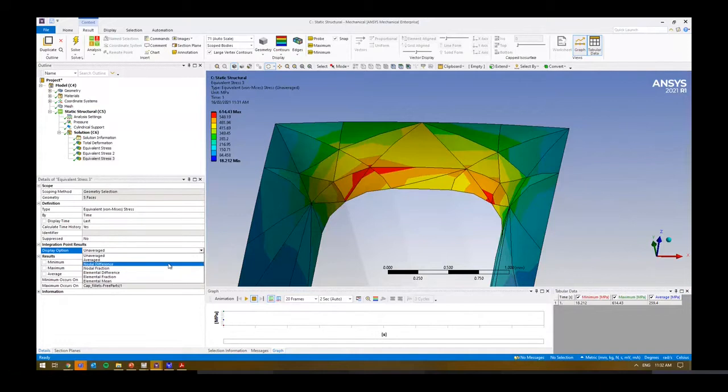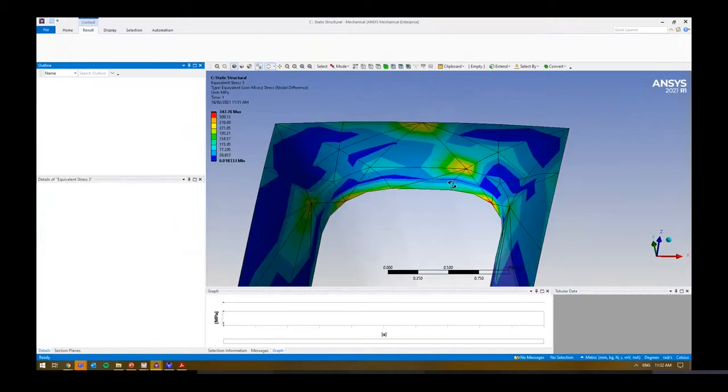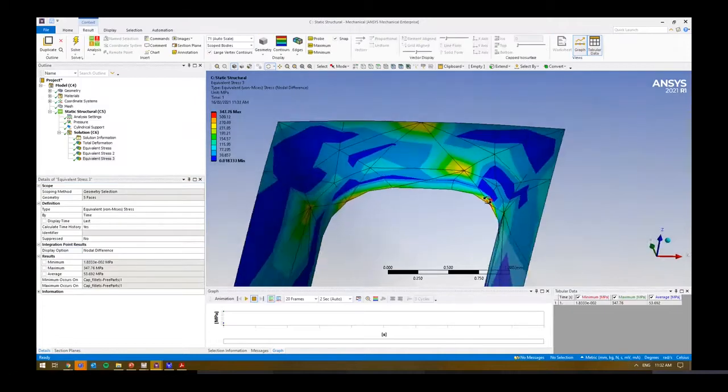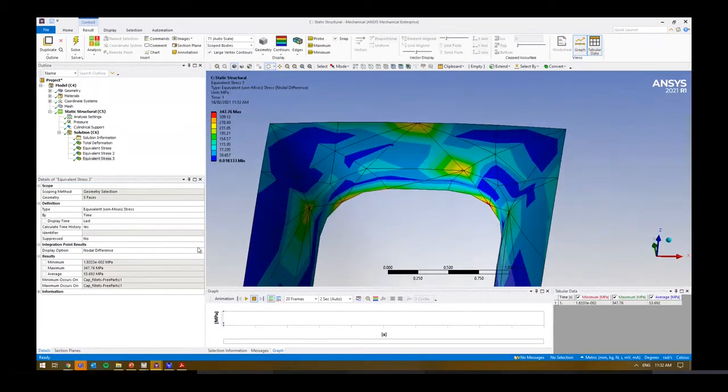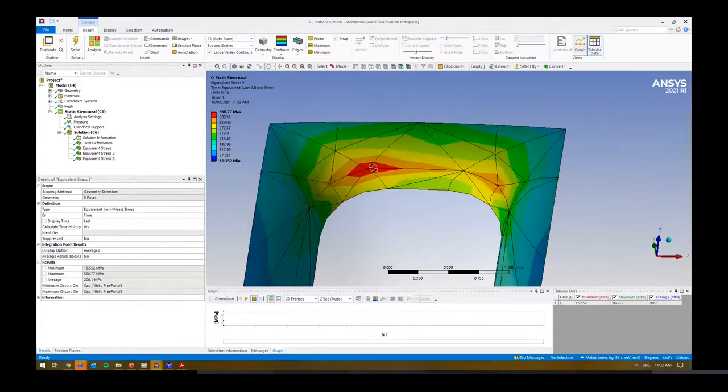We can also look at things like the nodal difference as well. So if there's a large difference between some of those components, we've got pretty large stress differences around here. And this is, again, another way that we can identify if we need to go in and make some changes, right? But generally, when I look at this, I try to make sure...